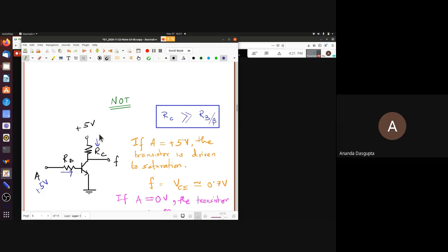The current through the collector, of course, will be beta times larger. If you wanted the transistor to stay active, you would want the collector to stay above the base in potential, which would mean that despite a current which is beta times larger, the drop across RC should be less. That is, if you wanted the transistor to stay in the active region.